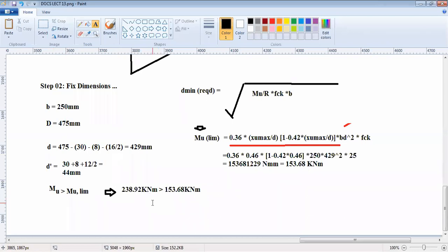In a singly reinforced section, what we used to do is increase the size of the section, the breadth and the depth. But here in the doubly reinforced section, you do not have that choice. You are not able to increase the dimension of the section. What is the other way around? You could increase fck, but there may be a limit to the amount of fck that you can increase. It may be dependent on various things, like for example, you have design mix. When you are preparing a design mix...